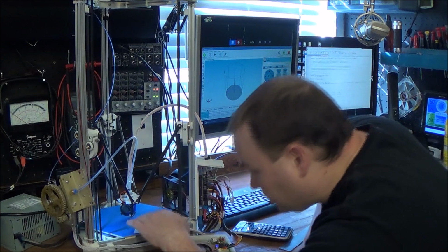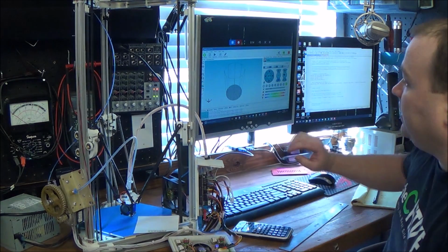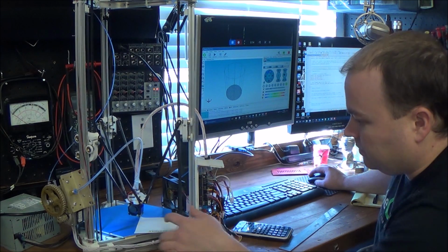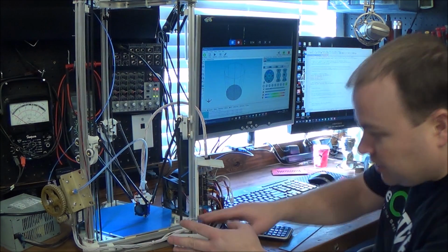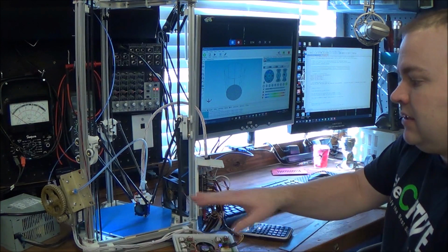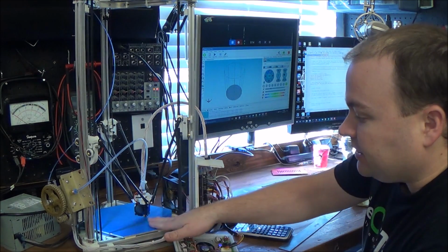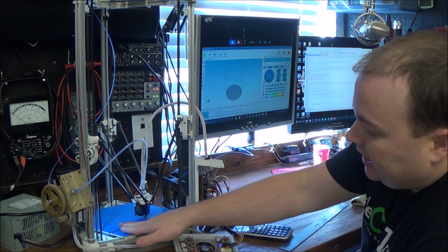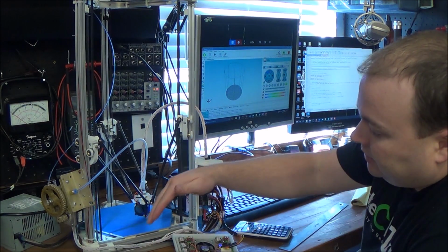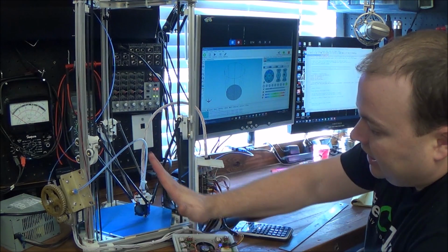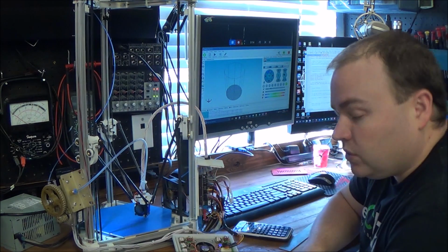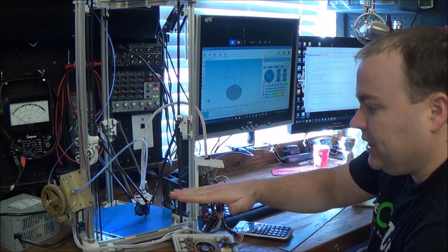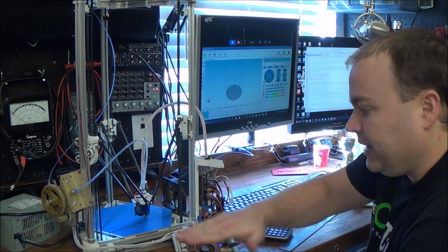What you're going to do is visually look at that and then jog it from side to side. So we're going to go and observe to see if it's flat. If our printer radius is off, the head could move in a convex or concave shape. So we've got to adjust that. And then once we get that perfect, we need to adjust how level the bed is.